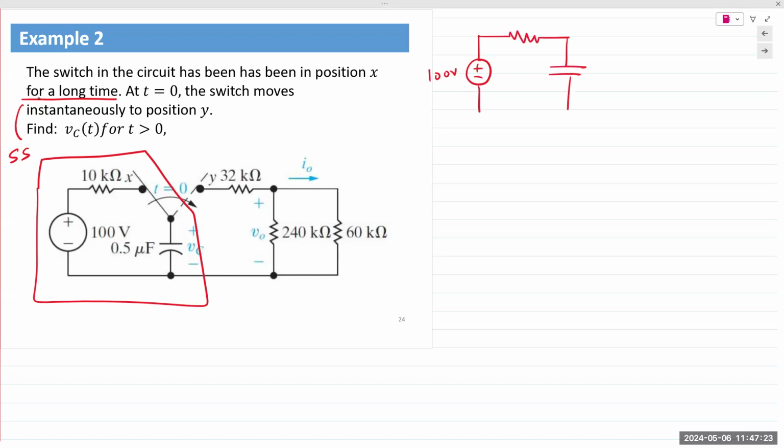Resistor. And similar to the question asked previously, it doesn't matter that the resistor is in series. At the beginning of the problem, again, we are not concerned with what happened before the switch was flipped. So before the switch was flipped at time t equal to 0, the capacitor is connected to the voltage source. Because it's been in steady state for a long time, eventually the capacitor voltage did reach 100 volts at some point in time.